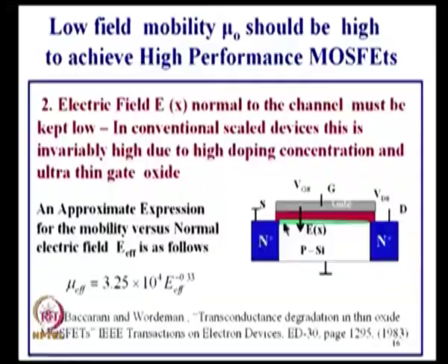How do you compress the channel? Take a look at this. By introducing nitride on the top of the gate, I can stretch it. I can compress it if I introduce germanium into the source and drain region. Source is silicon. During diffusion, you can add a little bit of germanium also. So, this will be silicon germanium, with a small amount of germanium concentration.